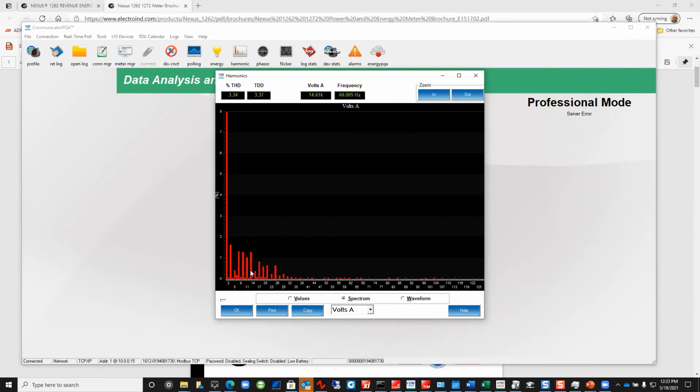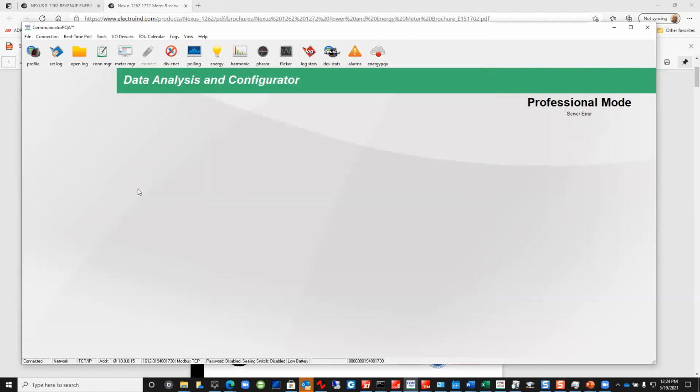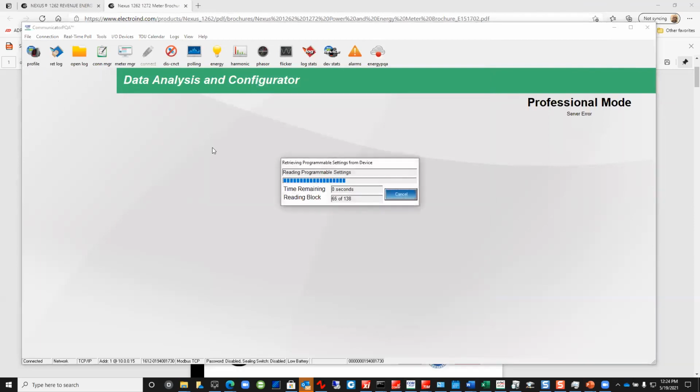Internally, if you put in a UPS, it produces a clean output. So downstream, the equipment that you have the UPS connected to is getting the right voltage or sine waves that you're looking for. But on the outside, what's going out to your next door neighbor, your customer, whoever is on your utility, they're now seeing all the noise that these are producing. So the goal again is to use power quality equipment like the 1500 plus and 1450 that can capture a lot of these types of events.